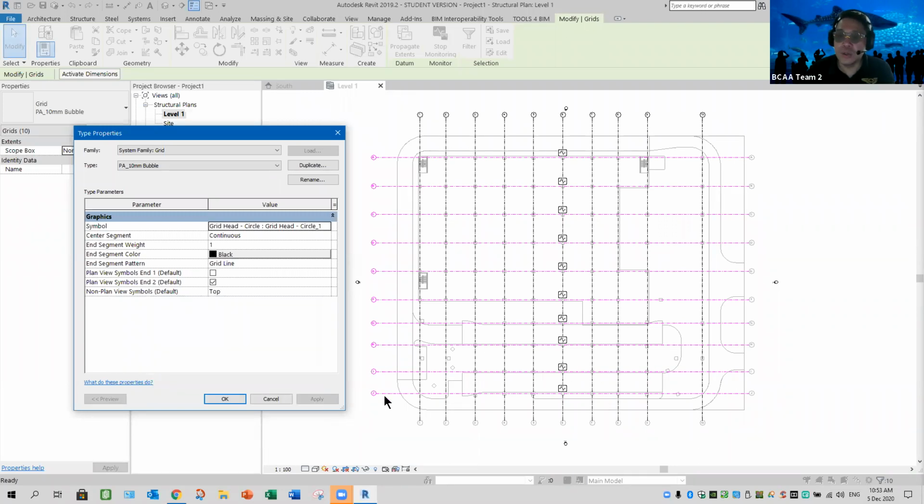That's why it's here. So when you draw grid line, depends on the point you select. So default is always adjust at N2. That means next time you want your bubble to be on the left, the first point must be on the right. So all this can be toggled.